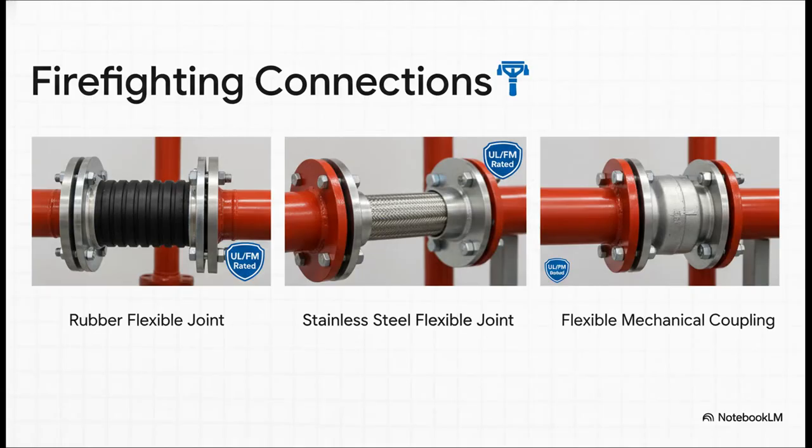Now, for firefighting systems, this is where the stakes are the absolute highest. The solutions might look similar to the ones for chilled water, but there is one massive difference. They have to be certified. We're talking UL or FM rated. This is non-negotiable. That certification is your guarantee that it can handle the extreme pressure and heat of a fire.